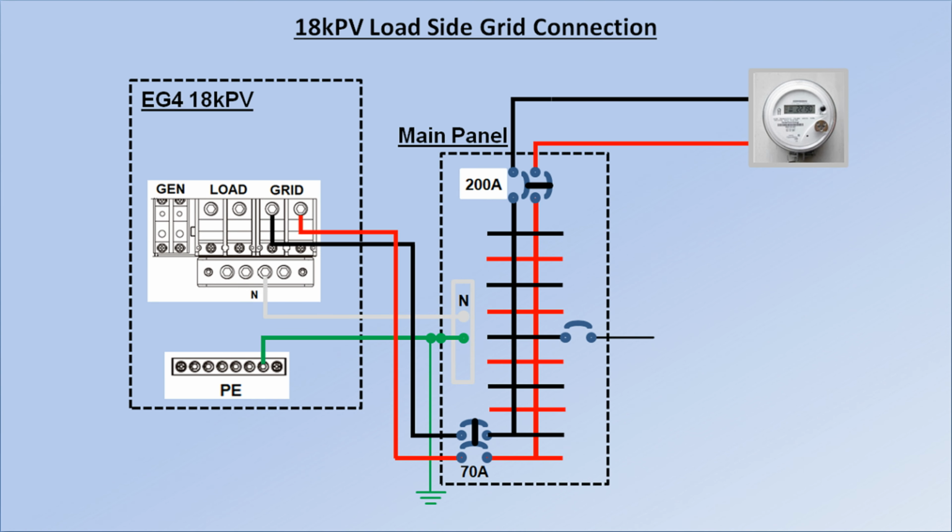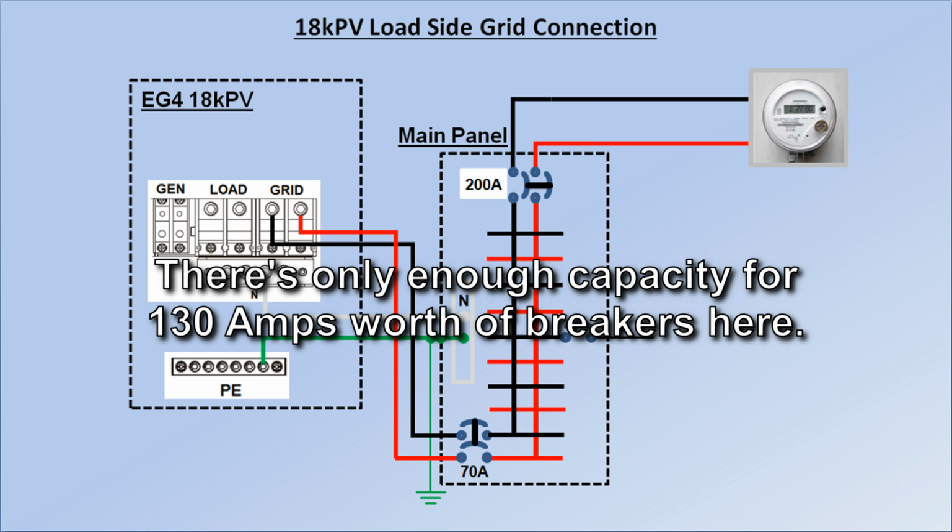So with this option, we'd add up all the circuit breaker ratings on the bus bar, and as long as the total doesn't exceed the bus bar rating, we're good to go. As long as the bus bar is protected by a main breaker that corresponds with the rating of the bus bar. This wouldn't work for many or most main service panels. If you have just 10 20 amp breakers in a 200 amp panel, there's no capacity available to add an inverter. The only place I might consider using this option is on the house meter of a multi-unit dwelling.